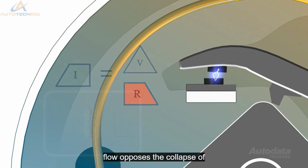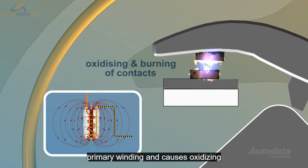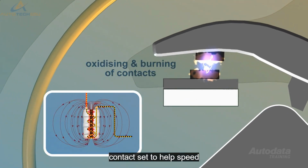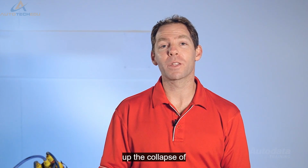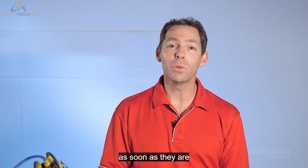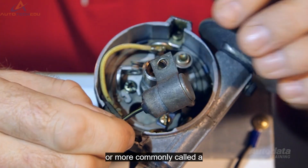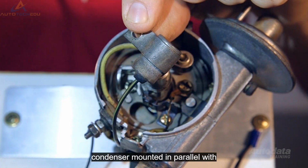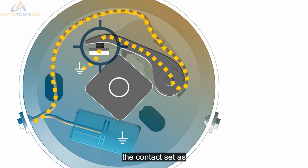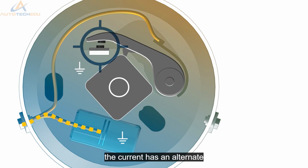This continuous current flow opposes the collapse of the magnetic field in the primary windings and causes oxidising and burning of the contact set. To help speed up the collapse of the magnetic field, we need to stop the current flow across the contacts as soon as they are open. This is done with the use of a capacitor, or more commonly called a condenser, mounted in parallel with the contact set. As we know, electricity can be a bit lazy. With a capacitor in the circuit, the current has an alternate path to travel, rather than jump the high resistance air gap.